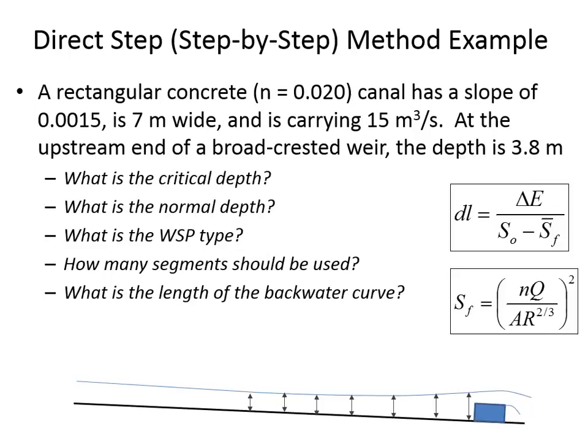Yeah, this is 3.8 meters minus 1.195 meters divided by the 6 segments. And so I know that I don't want the change in elevation of the water to be more than half a meter in any single step. So by doing this, I found I should have at least 5.21 steps, and I'll round that up to the nearest integer, because I don't want them to be larger. And so this tells me the elevation difference. Using this number is how I calculated each of these depths.